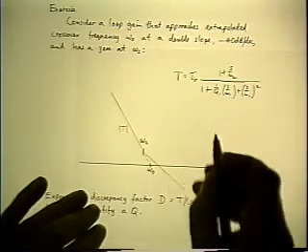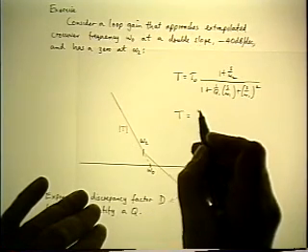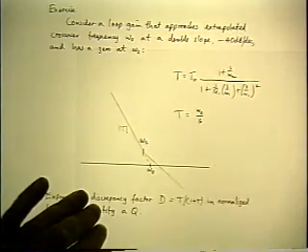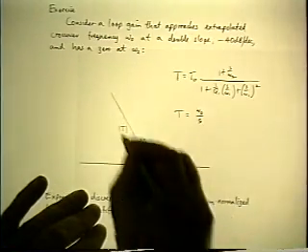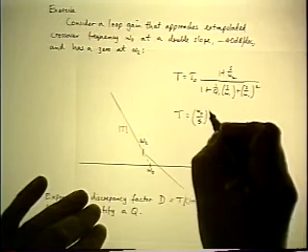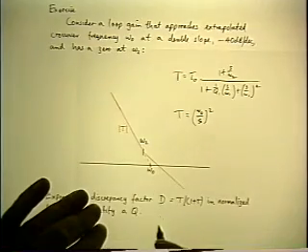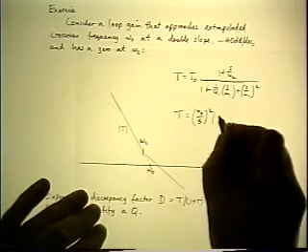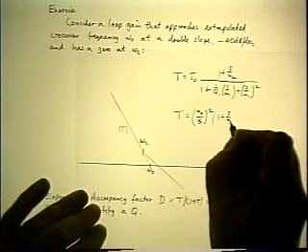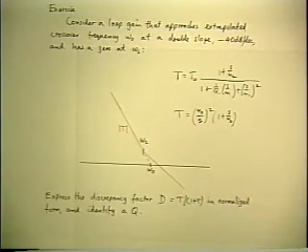So, using the omega 0, the expression for T that we need is omega 0 over S, because this is a declining slope. And because it's a double slope, we'll have to square it. And that identifies the left-hand asymptote, and then we just multiply by the 0. And that's all we need for the T.